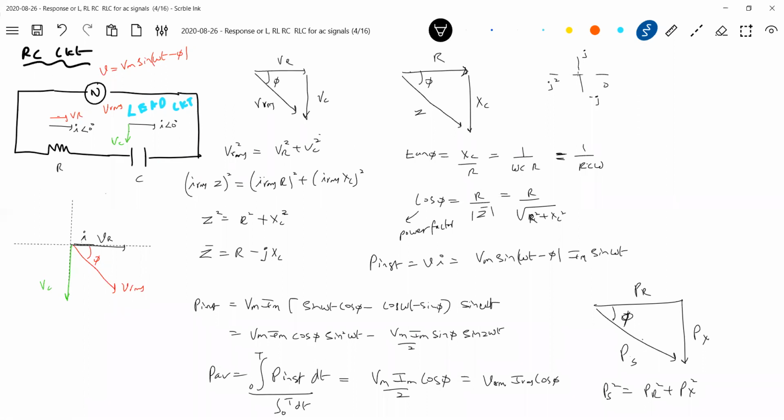So what is the power factor again? Power factor depends on these quantities. By varying capacitance, can you control power? By varying resistance, can you control power? Power dissipation in the circuit: by varying frequency also, we can control the power dissipation. Now, again, what is P average? This P average is nothing but IRMS square R. Somewhere in the corner, I'll write it.